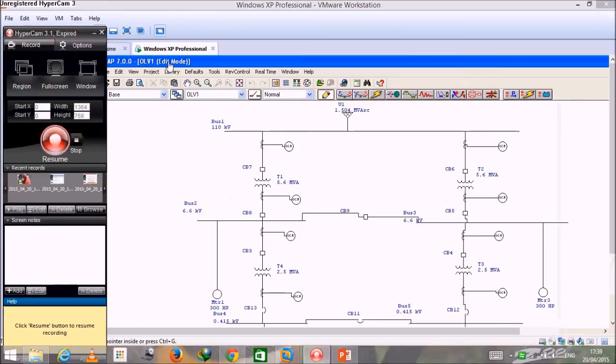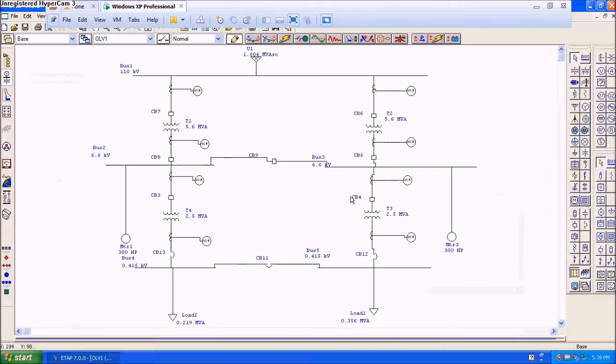So now here I'm going to show the load flow analysis. Now here you can see the values of load flow, which are red in color. You can see the impedance values which are given by J, and similarly the current will flow from upside to downside. And now we will show you how we will put the settings of each and every device. First we will see how to put the value in the feeder.